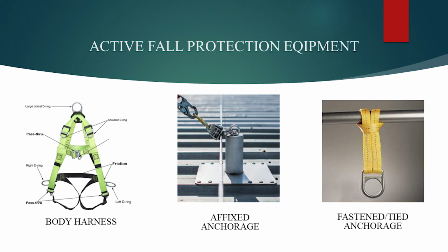Anchorages are points at which an anchoring device is attached, fastened, tied, or connected to a support location. There are 2 types, affixed anchorages and fastened or tied anchorages. Secure anchor points are the most critical component of fall arrest equipment. Installation of temporary or permanent anchors may be necessary, depending on the task being performed.